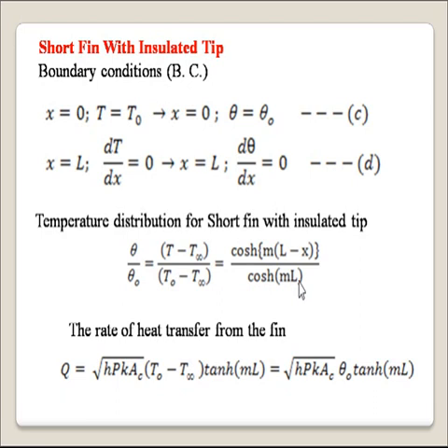For the short fin with insulated tip and the short fin with convection at the tip, we will not discuss the detailed derivation of temperature distribution and heat transfer, but we will directly see the boundary conditions, temperature distribution and heat transfer. So this is the equation which gives the temperature distribution for a short fin with insulated tip.